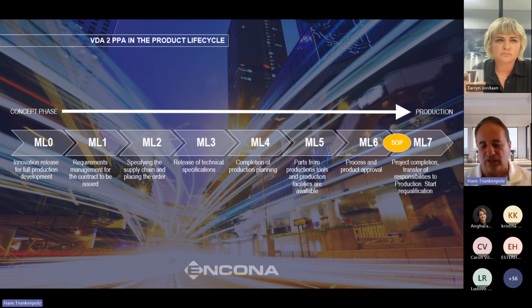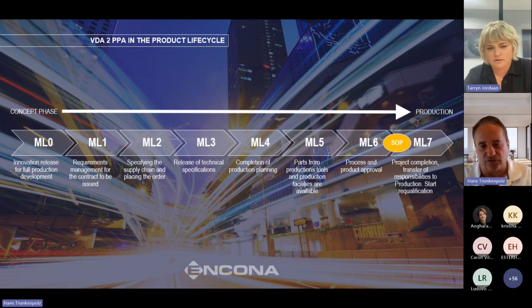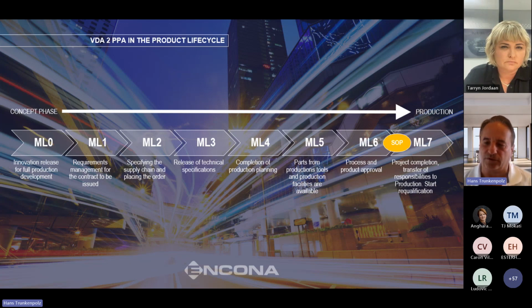Well, typically how it's meant to be, the use of core tools is stipulated in every OEM's or customer's specific requirements. Traditionally you can say that if you deal with an American OEM or a big American company like Lear Corporation, you're most likely linked to the PPAP rules, because that's AIAG, the North American side. If you deal with Mercedes or Volkswagen, they will ask you to do the VDA guidelines. The problem is that AIAG and VDA don't have a mutual recognition. They started now with the FMEA. The FMEA has been the very first core tool where you see a harmonized version between AIAG and VDA, so both recognize this particular way.